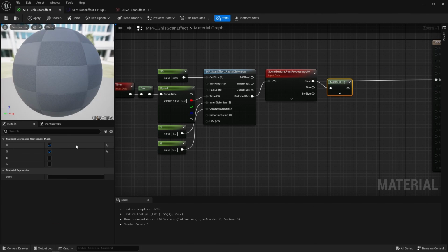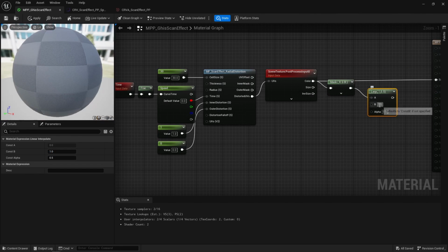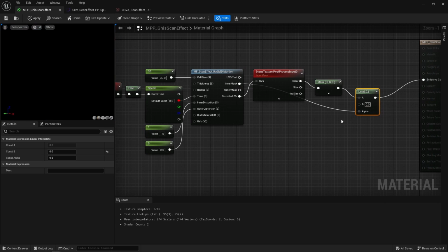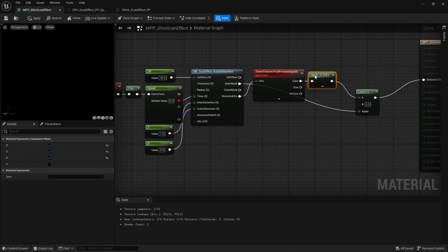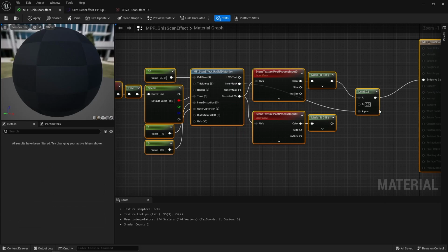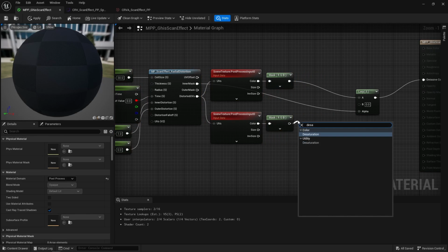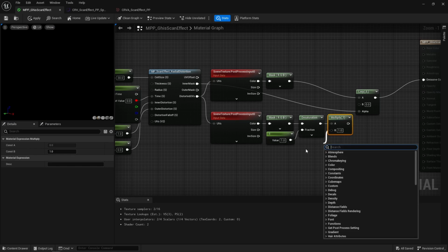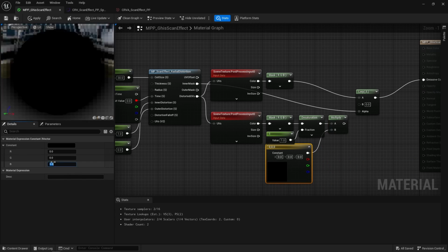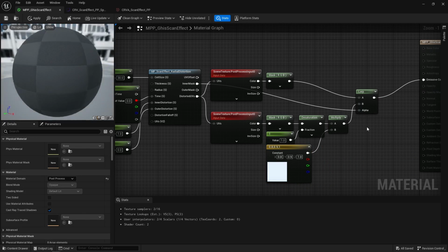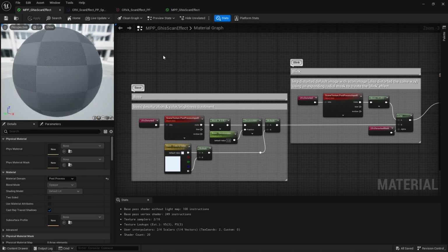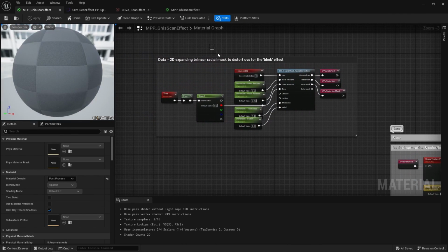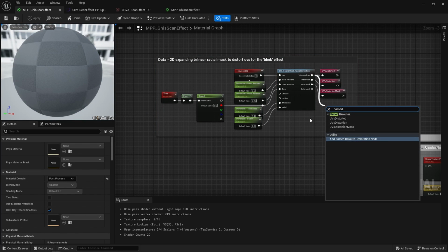Then I'm going to lerp this with a black color using the inner mask for the alpha value. Cool, instead of lerping to a black color though, let's sample this post-process input again, make sure it's distorted as well, and apply some basic color treatment. A simple desaturation and a multiply with a color will do the trick. Alright, fast forward a bit, I actually haven't changed anything, just made the graph much cleaner using named reroutes.